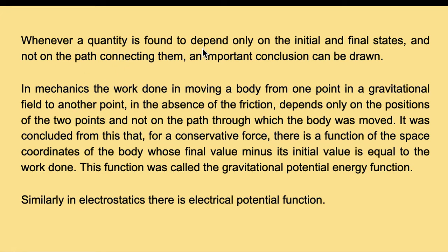Whenever a quantity is found to depend only on the initial and final states and not on the path connecting them, an important conclusion can be drawn. You can call such a function a point function if it does not depend on path, and if it depends on path, it is called a path function. So adiabatic work done is not a path function. In mechanics, the work done in moving a body from one point in a gravitational field to another point, in the absence of friction, depends only on the positions of the two points and not on the path through which the body was moved. It was concluded from this that for a conservative force, a term already known to you,